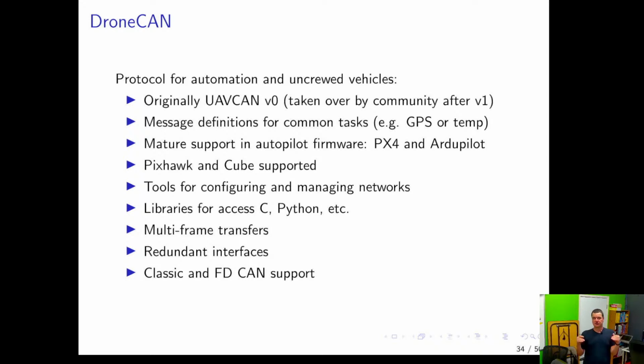There's two ways to configure this. You could either have it redundant, where it's sending the same data twice, so if one gets cut, you still have the other one. DroneCAN does not support the second mode, but typically with these buses, you should be able to configure one as a critical bus for your main things, like your gyro, and then a lower one for the lights or some kind of thing that, if that bus failed, it doesn't matter. But generally with big drones, well, it doesn't matter.